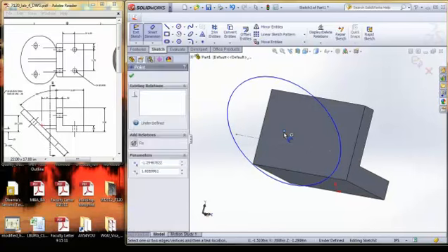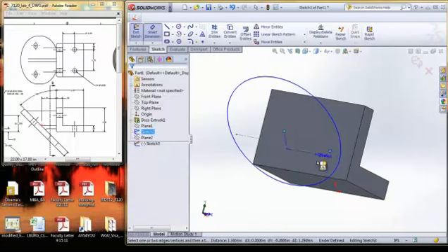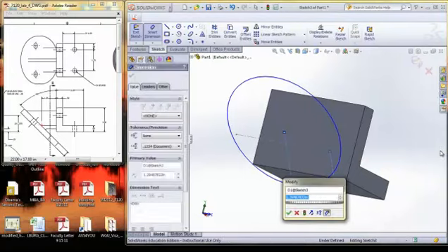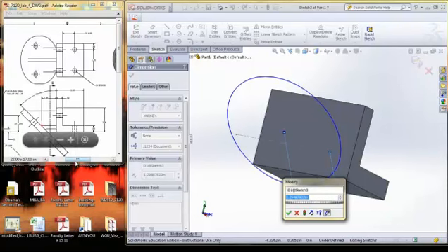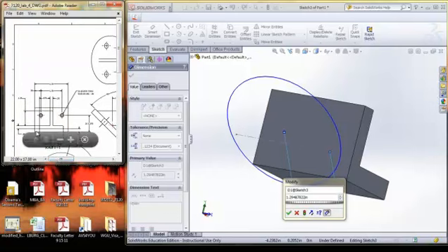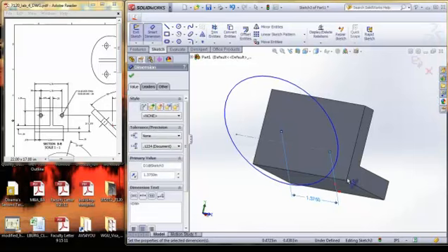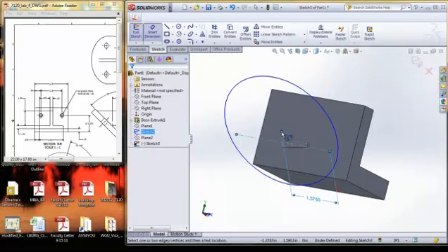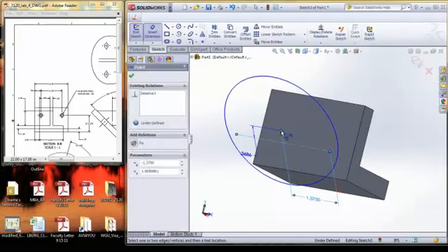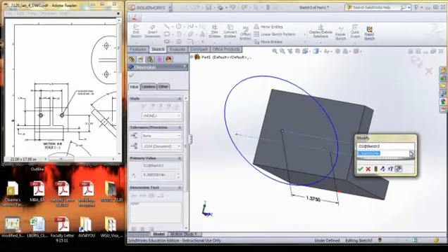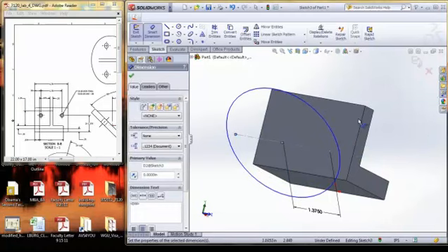And I want to get this center point, and I'm going to go from this edge. Well, the distance of that line was, if we look over in the other drawing, 2.75 over here. Remember, we went from edge to edge, so it was 2.75. So if we just come back over here and say 2.75 divided by 2, that should line that up. And then we'll grab this line and the center point again, put it in, and we'll say 0. Now we know that's lined up.